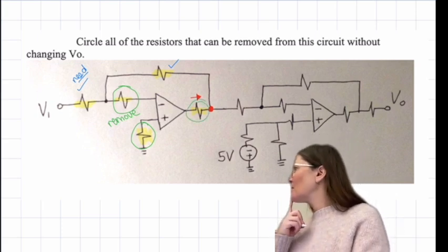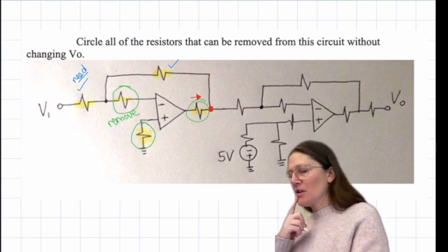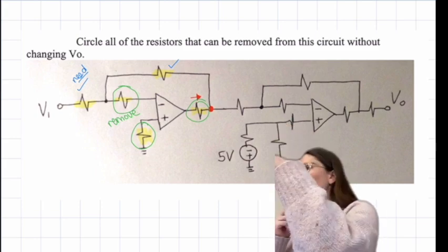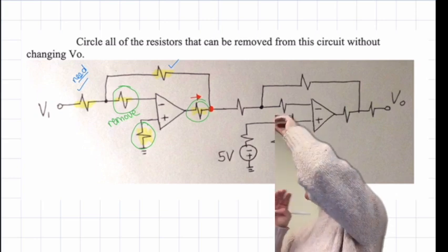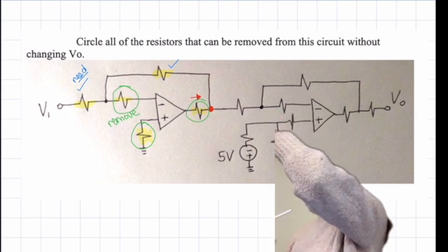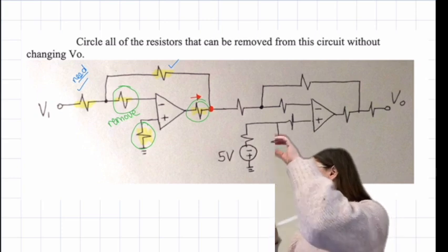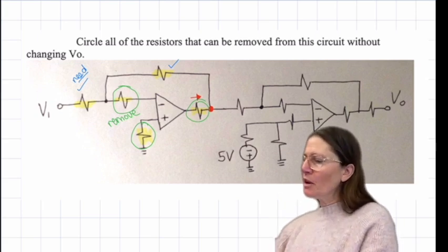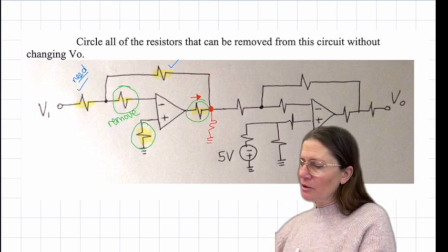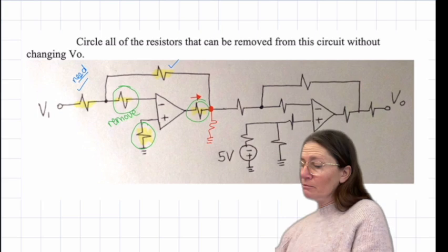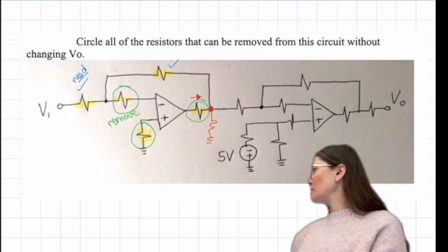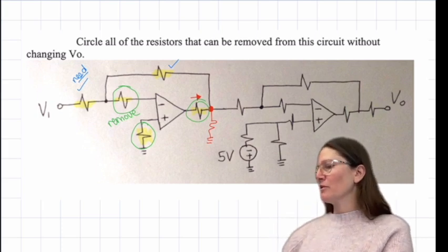Yes. So what if it was a switch comparator? Would it still be the same? Oh, okay. So if it's a switch and you had a resistor there, it's going to be whatever the supply voltage is. So if I had a 9-volt battery, it would be 9 volts, or minus 9 volts if I had plus and minus 9 volts. So it's still going to fix it there. And if I added a resistor with an LED to light it up, that would still stay fixed even with the switched comparator. So that voltage still stays the same.